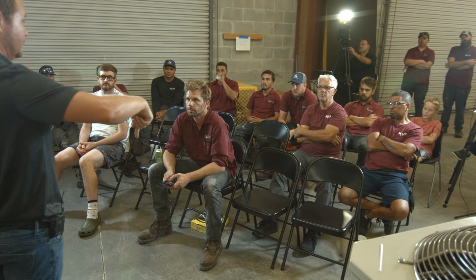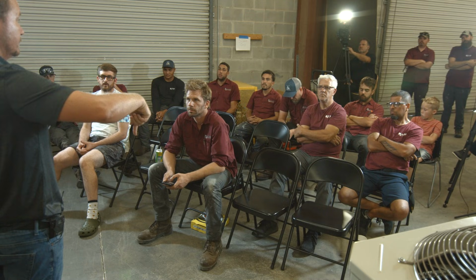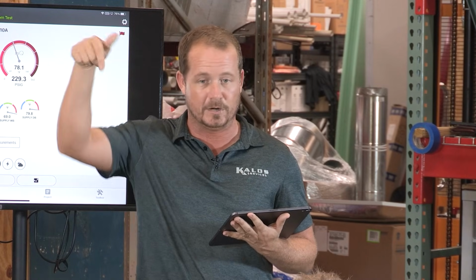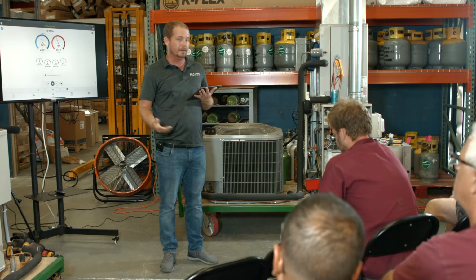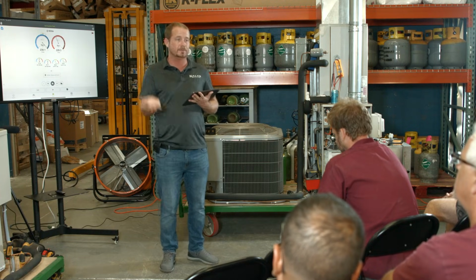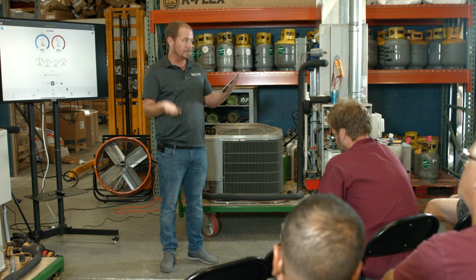So what's going to happen to the pressure inside that evaporator coil with no fins? It's going to drop. Why again? Pressure, temperature. No heat transfer. Because it's not having enough heat transferred in, right? It's the heat that's being absorbed into it that holds up that pressure. If you're not absorbing heat, that pressure is going to just keep diving and diving, right? Decrease in temperature equals decrease in pressure, right? We add heat to it, that holds the temperature up, that holds the pressure up. And we create this equilibrium.